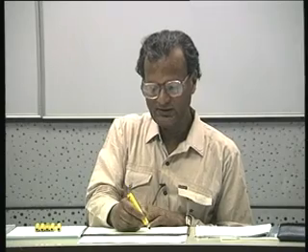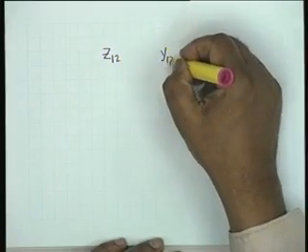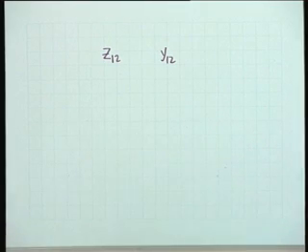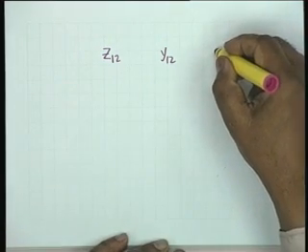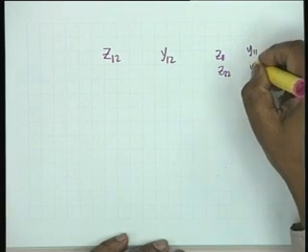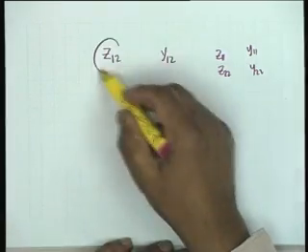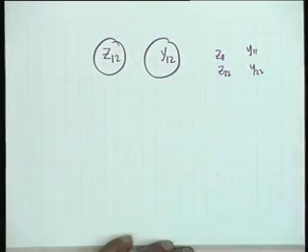Since all transfer functions involve z12 or y12, in addition to the driving point parameters, that is z11, z22 or y11, y22, the properties of which you already know because they are DPIs, it suffices to consider the properties of z12 and y12.